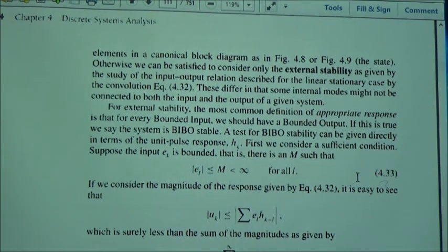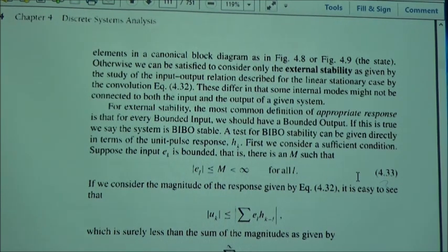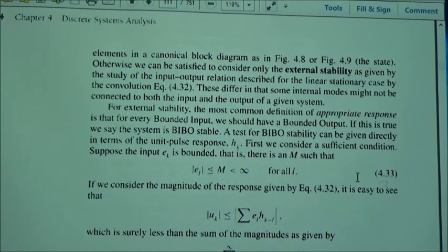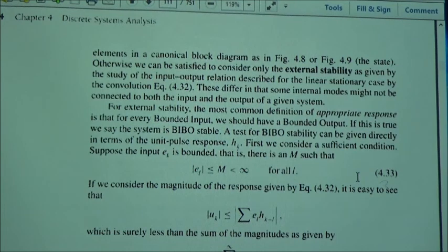You have seen it before in other lectures that the entire left half of the S-plane maps into the interior of the unit circle. And the j omega axis is going to be the circumference of that unit circle. And anything outside of the unit circle is unstable in the Z-plane. Same thing, any closed loop pole in the right half of the S-plane is also unstable. One is in continuous time, one is discrete time.